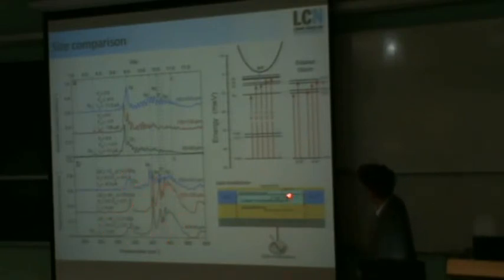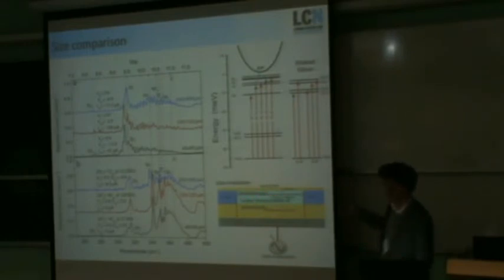So just quickly, why this is happening is that really by modulating your gate, you're changing the electrostatics in the region just near the backgate region. And as a result, that's the region you're sensitive to in your actual detection mechanism, and so you're actually looking at the donor concentration in that specific region.